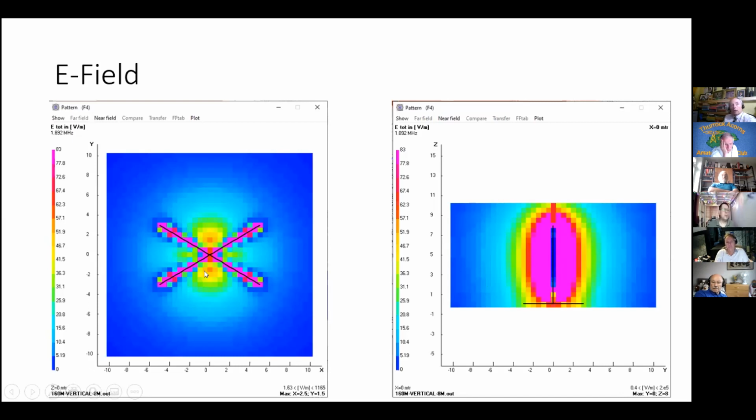So I think the takeaways from that is if you shorten an antenna, you effectively get the pattern starting from the open end back towards the feed point in the near field, and above ground radials are hot all the way to the ends, especially if they're electrically short.